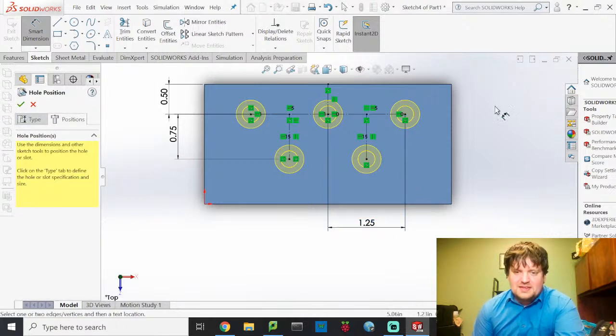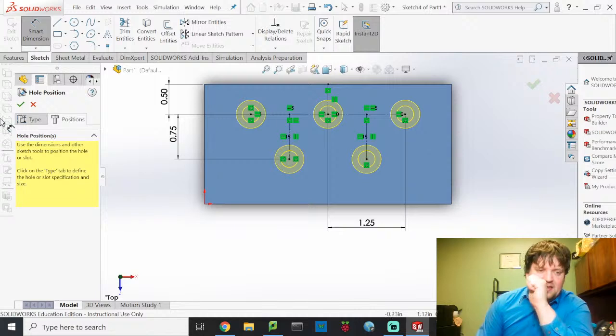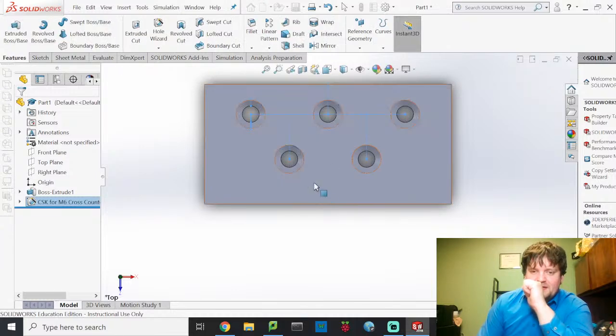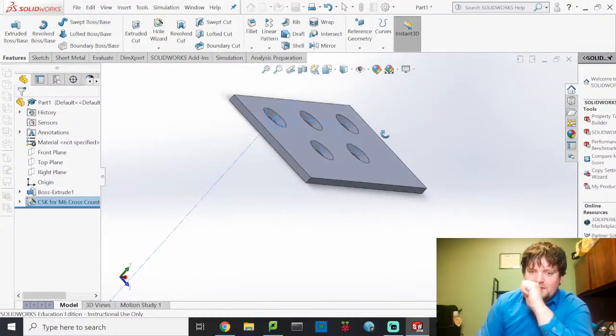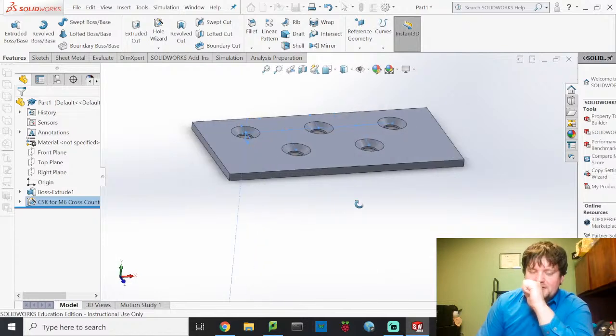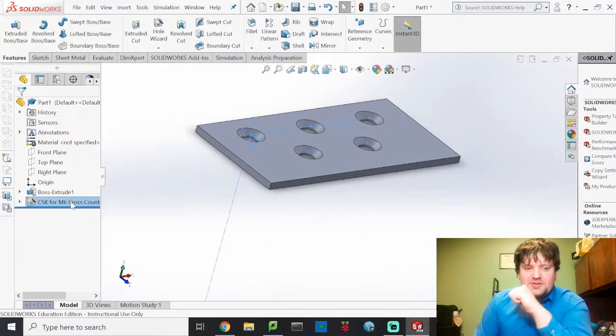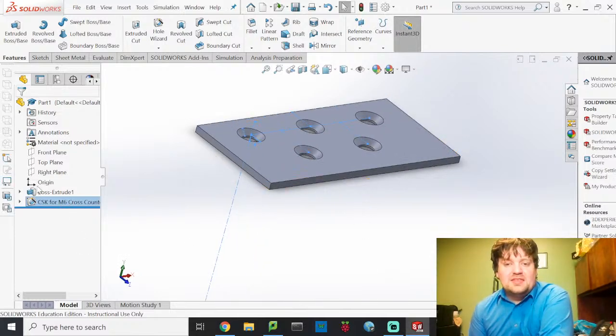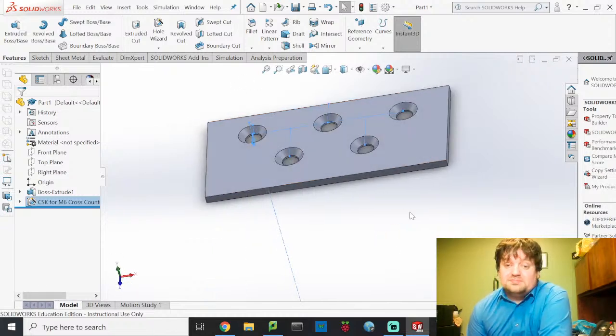Well, that's a nice hinge plate. So now when I go to hit yes, it'll accept these and it'll build my hinge holes. And they're already countersunk according to how it has fit. Now you'll notice that it comes up in the part tree as saying that it is an M6 countersunk hole. And that's the relations we have.